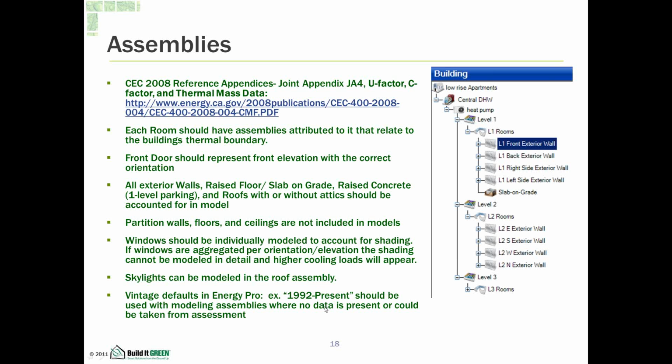So if each of the dwelling units have partitions that pop out and cover the windows to a degree, you can call it a side fin and it's giving shading. You won't be able to capture that if you add up all your windows. But if you have individual windows, you can capture the shading capabilities of each of those windows.